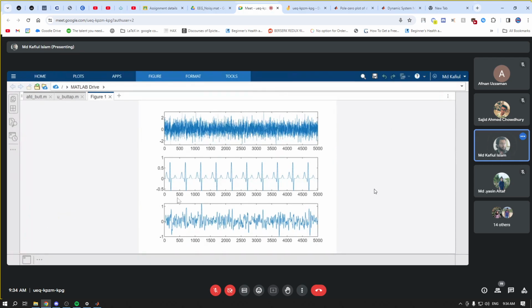So still it's noisy, but it was not there before, so we can somehow find out some of the peak. You see, these are the peaks during ECG, but we still cannot find out exactly the QRS complex point properly, right? Still very noisy. So that means that we can improve the filter, right? We can start using a different window function. We can increase the order of the filter and see if there is any luck or not. So we can actually try a different way.